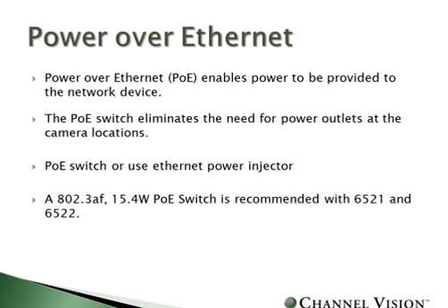As I mentioned, we'll talk a little bit about the power over Ethernet and what it is. The cameras will get their power from the device that's hooked to the network, whether it be their switch or their router. So you'd have to have a switch that provides power over Ethernet. That's on the RJ45 Cat5 cable that goes from your switch to the unit. Power will run on that.